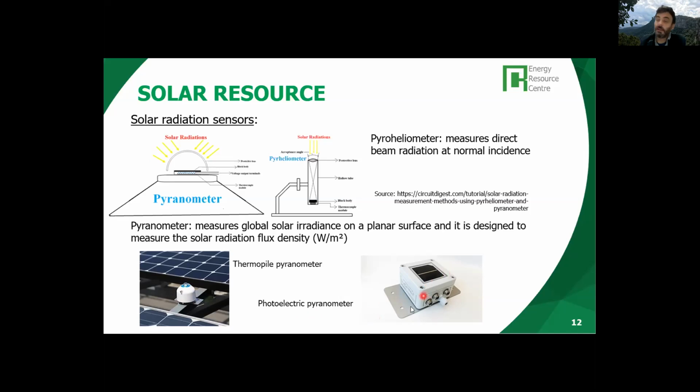They have a PV cell that is calibrated, okay? And these kinds of pyranometers are also very much found in PV systems, not only in solar parks, but also small PV systems. I would recommend installing a pyranometer, a solar radiation sensor that can help us control the levels of irradiance being received in the solar panels constantly. And then we can monitor that.